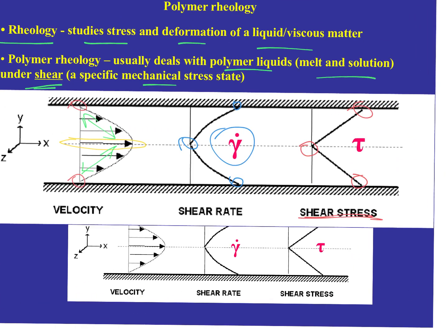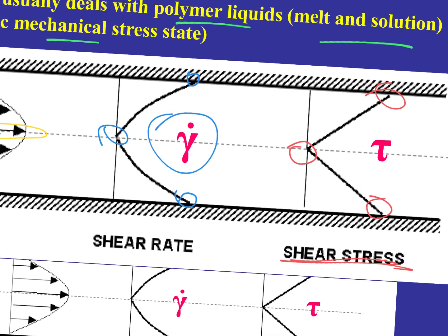So this is where I start talking about additives. So of course, and we've already talked about this, you guys remember the example of lubricants, right? And so what we do is we get that external lubricant in there, and it precipitates out on the walls, all right, as a discrete low molecular weight compound that separates the chains from the walls, or at least tries to.